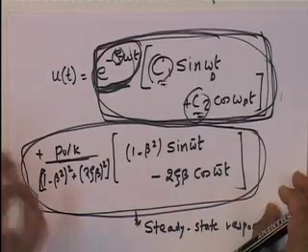However, even if you have very low damping, at some point of time that transient part will be damped out and you are left with steady state. So, although an undamped system does not have steady state, you can take a situation where xi tends to 0 without it being undamped.